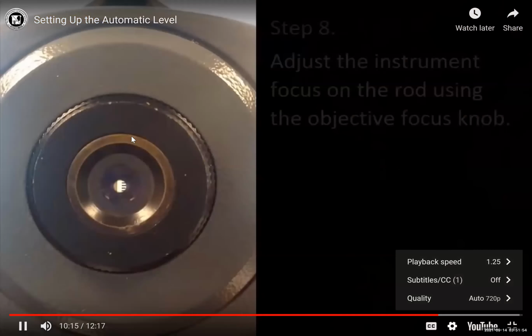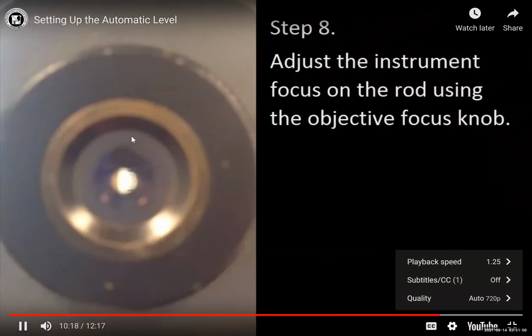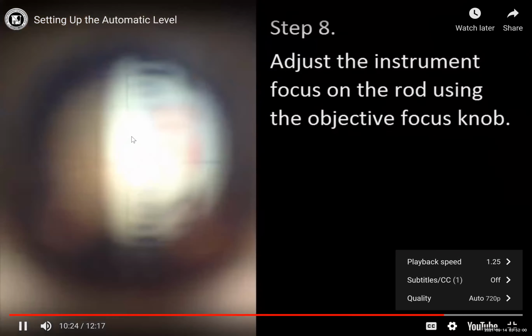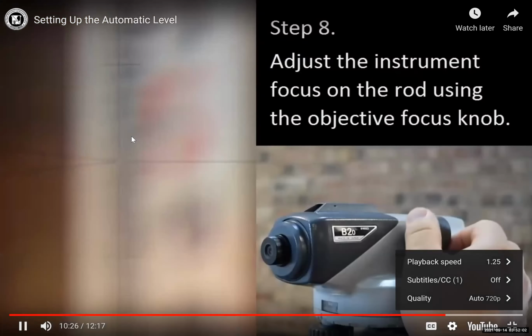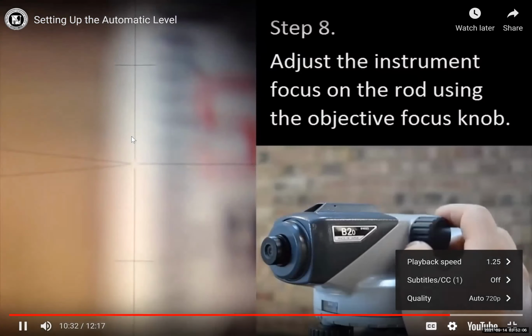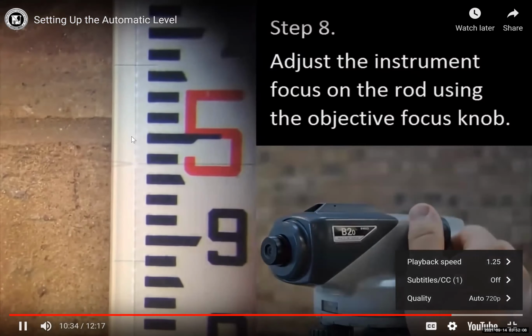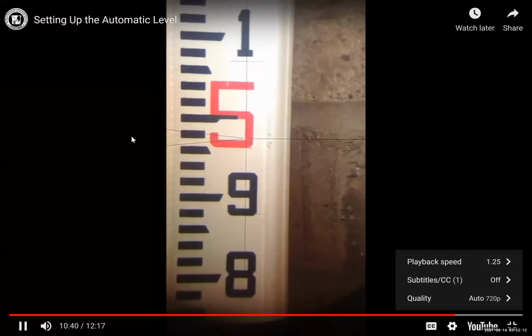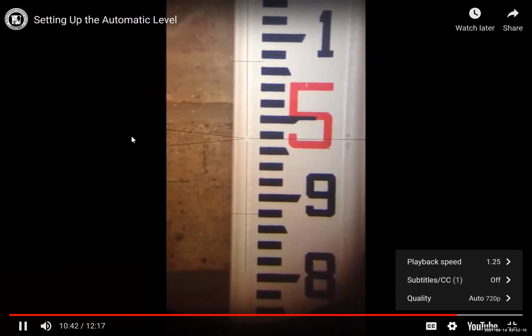Your first look through the instrument usually gives a blurry view. So adjust the objective focus knob, that is the biggest knob, until you see the rod markings. With your slow motion screw, refine your aim until the crosshair allows a reading.